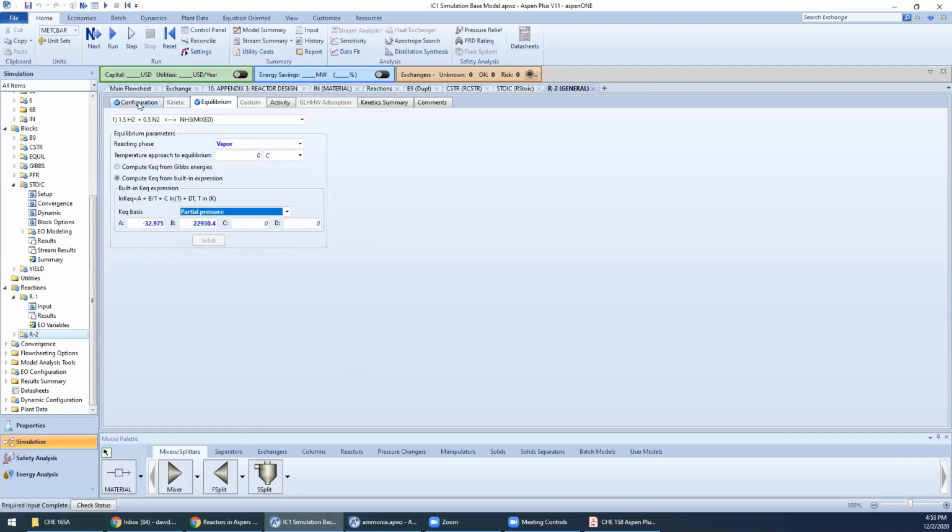What if your equilibrium law doesn't follow the expression it has? That is a very good question because that trips up a lot of people. If it's in another form, but you still have an equilibrium expression, you have to put it into this form. Oh, okay. And so what I've done is actually taken a different type of expression and forced it into this one using Excel.